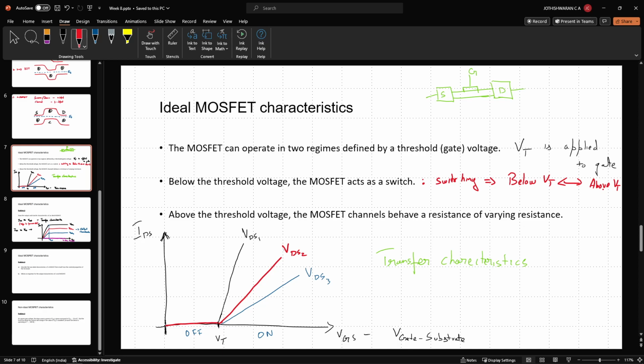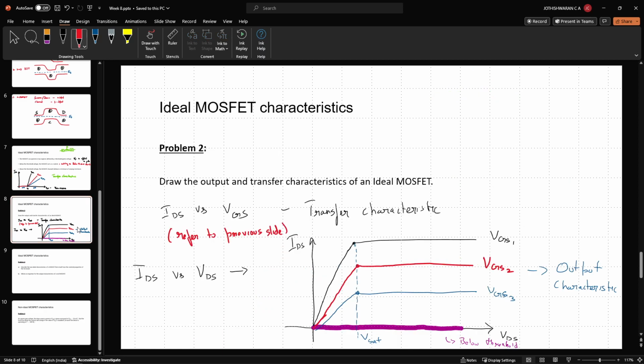So the gate voltages are the things that are switched to achieve the switching effect. So there is a clock pulse, and that usually feeds into the gate voltage of the transistors. And there is an initial VDD or VDS that will ensure how much current flows through the device when the device is turned on or off, depending on the value of VGS that we reach. Okay, so this is the ideal operation of a MOSFET.